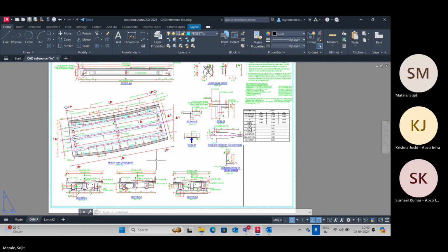But when I went to my professor and said I cannot really deal with these codes, he told me this story. Any finite element program should have nodes, should have elements. So you start with the definition of nodes, elements, material definition, cross-sections, assign cross-sections to them, build the geometry well, apply the loads well on top of it, and your work is done. What you need to further know is only the interpretation of results. Clear?